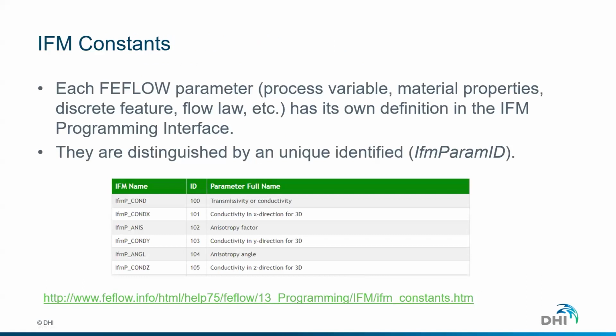And every parameter in FEFLOW, every single detail that you will see in the GUI, so if you are setting your problem class to confined or recharge, or even if you use phreatic and then define the number of slices and which slice has certain properties, every single detail has a name in the Python interface, has a constant, which is an ID or a name. And there is a list of these enumerators through our submodule called enum. This is interesting to know because it's easy to operate knowing these constants. I will show you a trick how to get access to those in parameters.